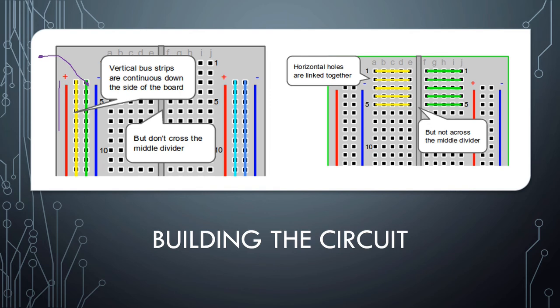Looking down this negative side rail, all of these little holes are connected. So if I ground to one place, anything else here that feeds in will also be connected to the ground. Anything else on this green line. And same for the red, but we really don't need to use that right now. It will just be important that you are grounding to the ground rail.